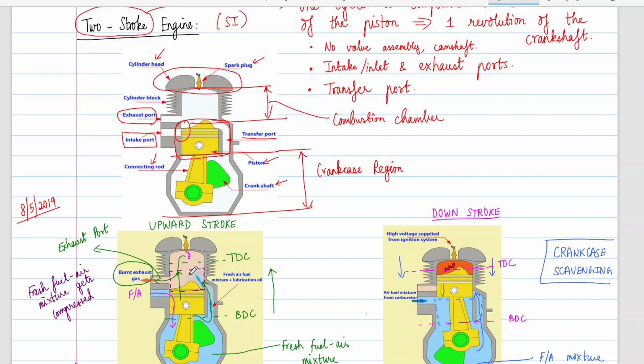One good idea, if I were to think aloud here, is that you take the burnt exhaust gas from, say, three cylinders and push it into a fourth cylinder to burn out the residual. It will, in a sense, enable you to get a little more efficiency out of the process. However, as you would see when the professor compares two-stroke versus four-stroke engines in class, it's a much better and much more efficient technology. So recent offerings from brands